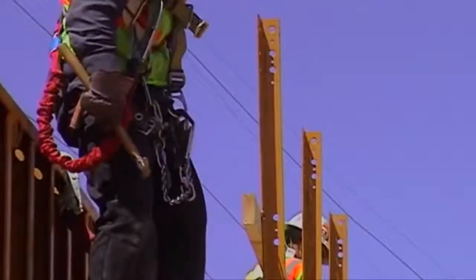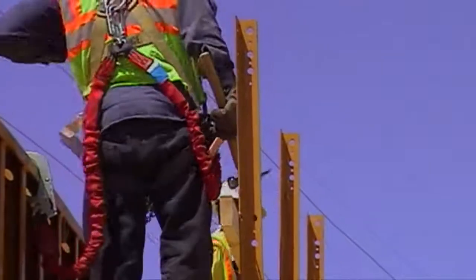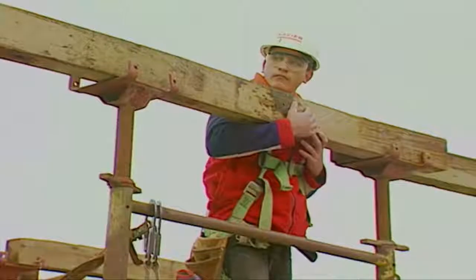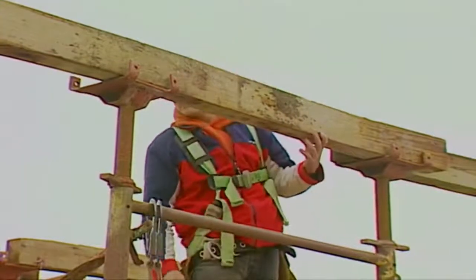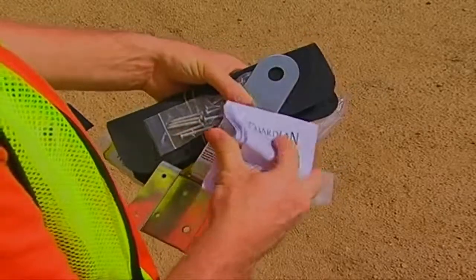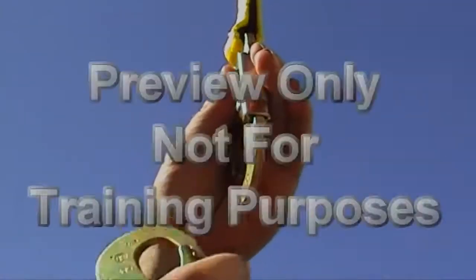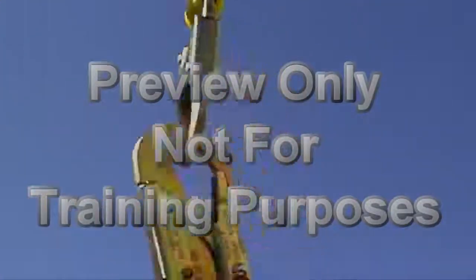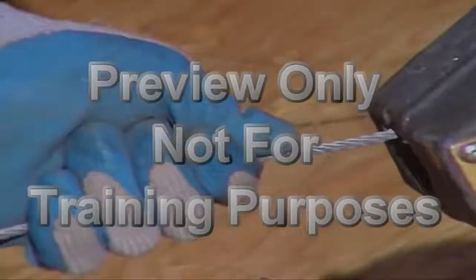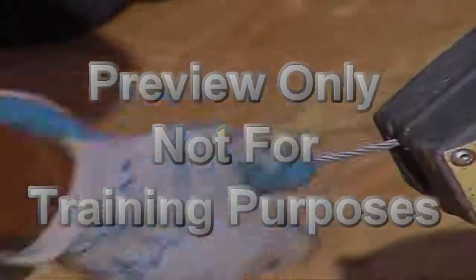Personal fall arrest systems used on scaffolds must be attached by lanyard to a vertical lifeline, horizontal lifeline, or scaffold structural member designed for the tie-off anchor. Vertical lifelines must be fastened to a fixed, safe anchorage point, not part of the scaffold, and be protected from sharp edges and abrasions. Never attach vertical lifelines to each other or to the same anchorage point. Horizontal lifelines must be secured to 2 or more structural members of the scaffold.